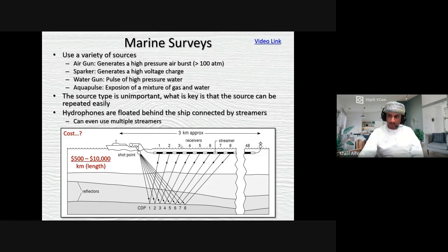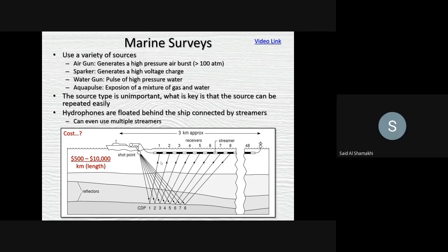The sensors are actually called geophones, which respond to change in displacement, which gives you the velocity. A change in velocity gives you what? If there is a change in velocity, what physical parameter do you get? Acceleration.